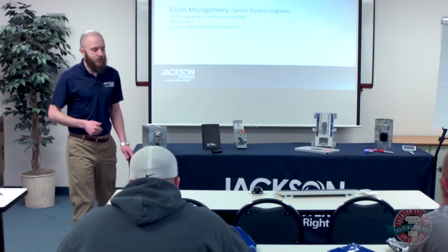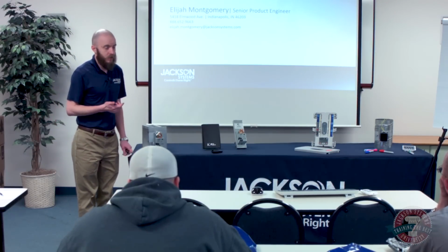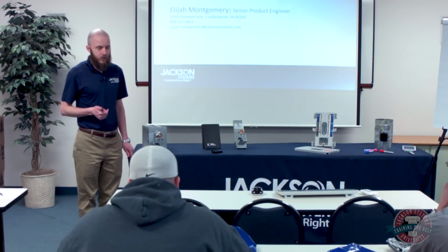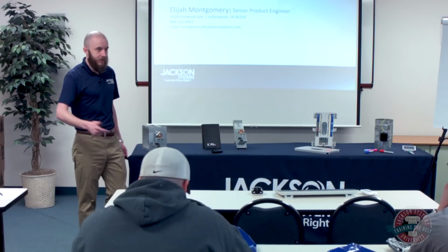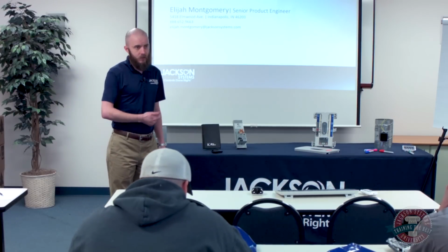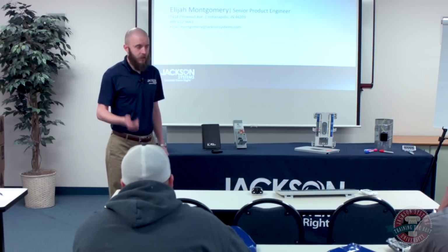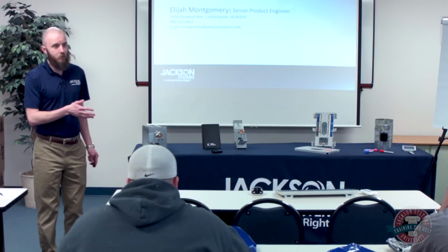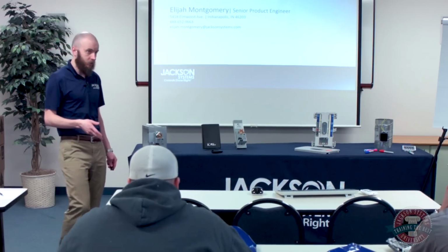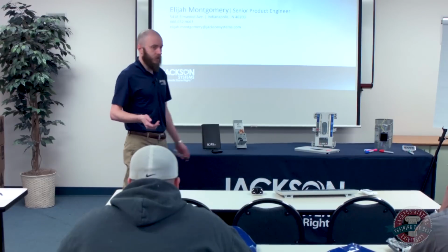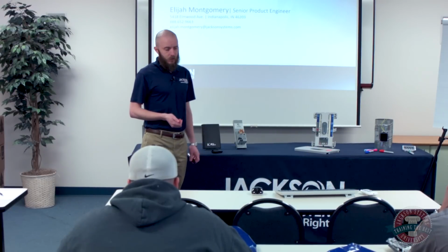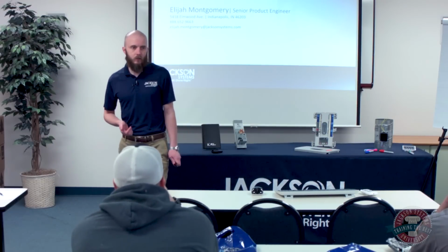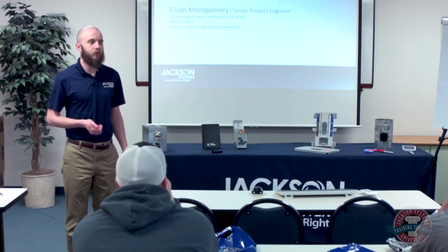In some cases, you could get by with having two transformers. You've got to be careful how you do it. On some of the older systems, a lot of times what we would do is on the damper outputs, instead of running that straight to the damper, we would just have that trigger a relay, and then we would feed power directly to the dampers from a larger transformer so that we weren't running all that power through the zone panel. So that's an option. You can use isolation relays to power the dampers directly. But I would recommend increasing your size rating of your transformer before I'd parallel two transformers together.